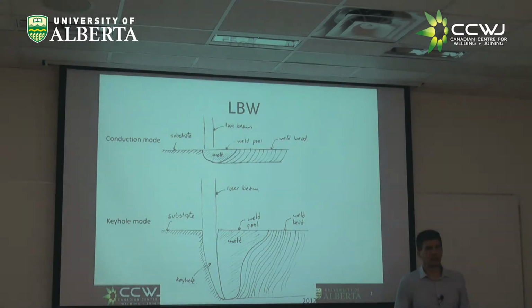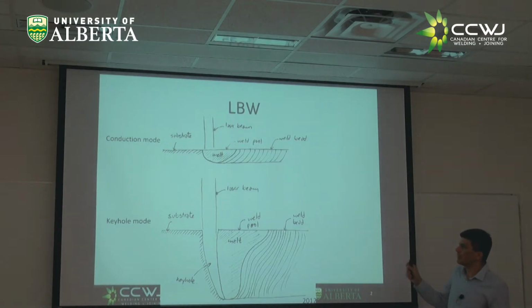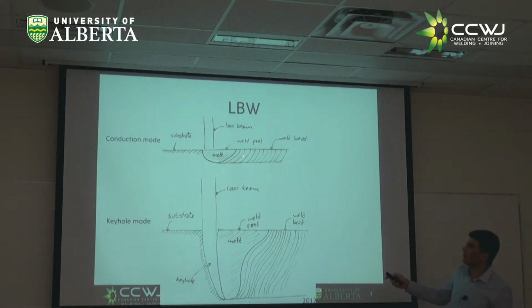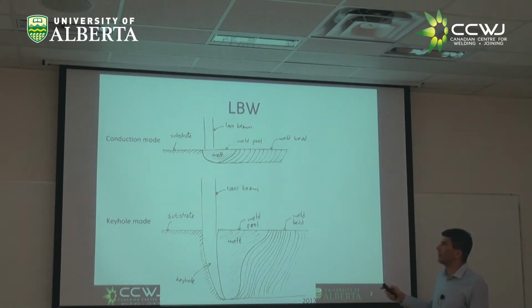And I mentioned to you that when people use 6010 electrode, that I don't remember if this week or next week you're going to be trying. Next week you're going to be trying that, right? Some people say, oh, here I have a keyhole. Yeah, kind of a keyhole. But this comes because you're putting an ungodly amount of power in a very small area, right? And you can imagine the type of weld you're going to get when you have a keyhole than when you don't is very different, right? So this is the first thing to know.